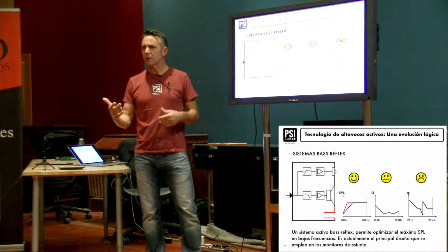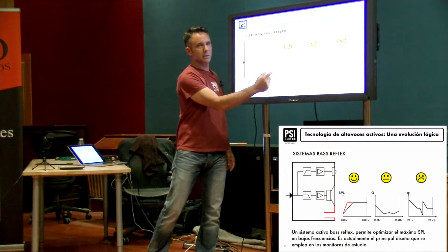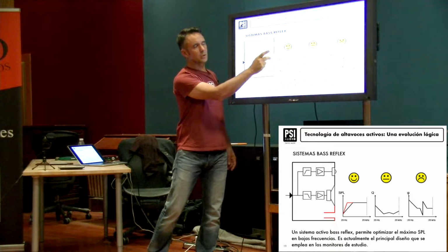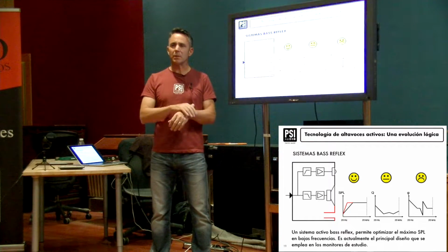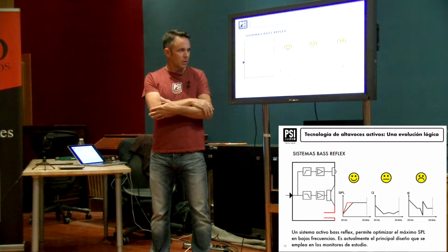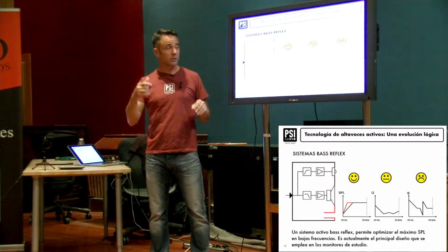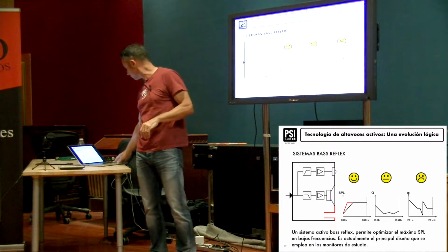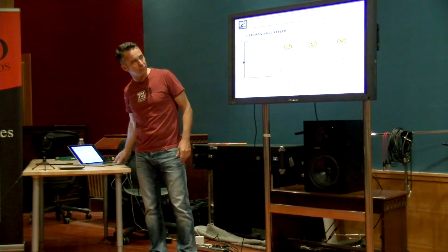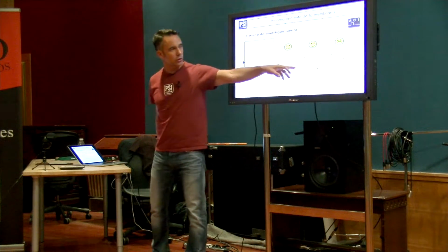And then bass reflex, of course, this mass here, you can use that, or you can use another passive driver that resonates also. That makes it a bit easier, but it's not quite as good with the inertia that's built into the system. Okay, so this is quite commonly used, and if it's well dimensioned, it works very well. Now we still have a few other problems. One of which is this distortion.